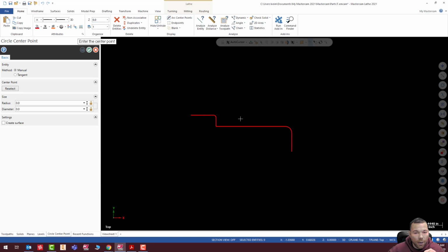So I need to technically be towards myself, or towards me, about 0.5 inches because that's where the hole lies on the diameter of the part. So I'm just going to add a 0.5 here into my Z, and this allows you to draw on a different Z level.